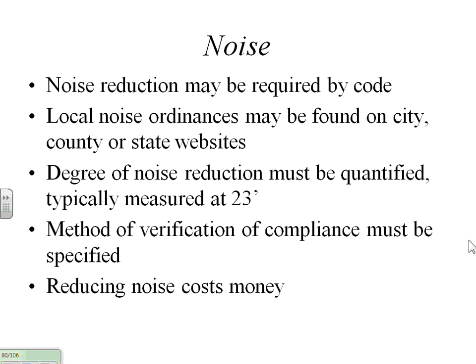And one thing that I always tell engineers when you write your specifications, yeah, give me the level that you want, the distance that we have to be at, but say at full load, because there's a difference between no load operation of the generator and full load. It gets a little noisier when you put load on it.